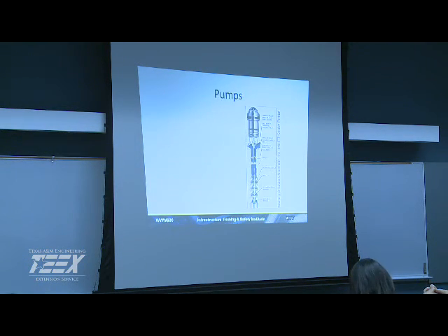Here's a vertical shaft, but the submersible is the same, it just has your motor on the bottom. Depending on how high you have to push the water and what kind of volume you're looking at, you're going to need a certain number of impellers, called bowls. We were running about 6 bowls off of a vertical shaft, pushing about 2.2 MGD off of each one, in 18-inch casing, so it's a pretty good size pump.